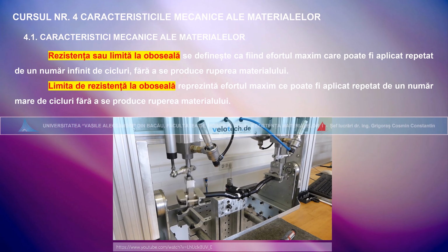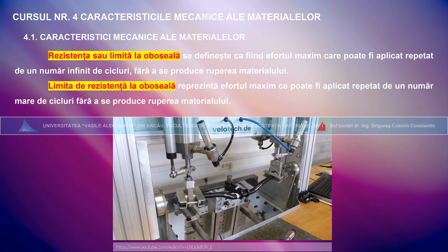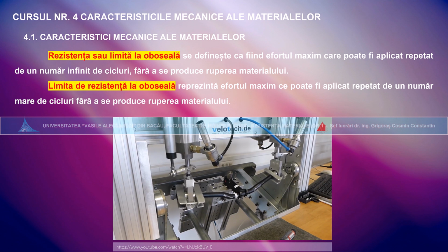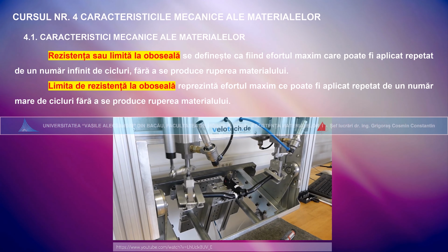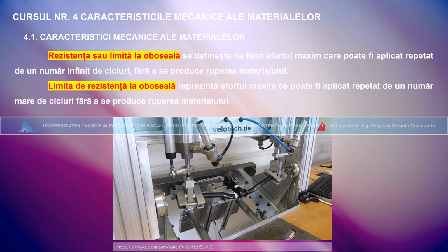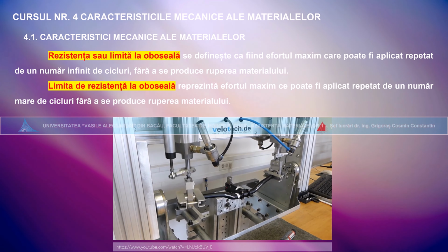Moreover, the fatigue strength does not only depend on the material. The mean stress has an important influence, the shape, the surface quality, environmental conditions and much more. Not an easy story.